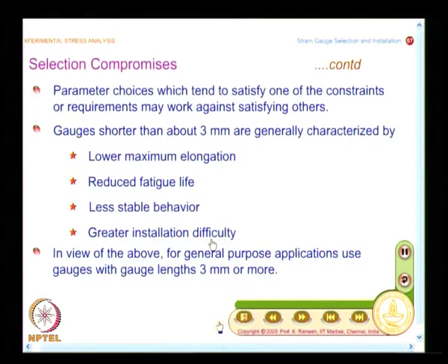Before you take up the discussion on strain gauges, you would have heard that strain gauge is a point by point technique, and you would have imagined I can find out what happens at a point precisely. What we saw was, from the way we have to make a strain gauge, I do not have a material which has very high resistance, wherein I can put a speck of material and measure what happens at a point of interest.